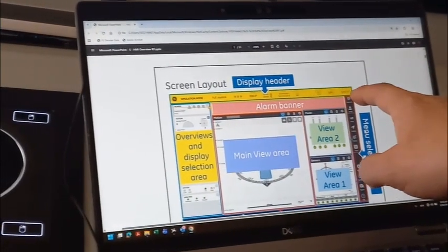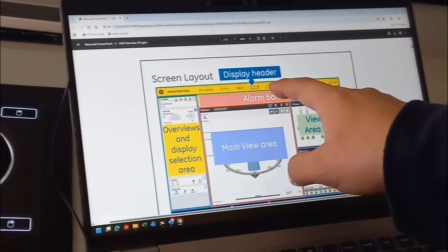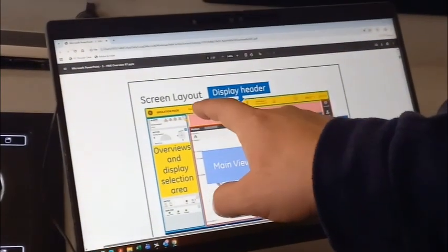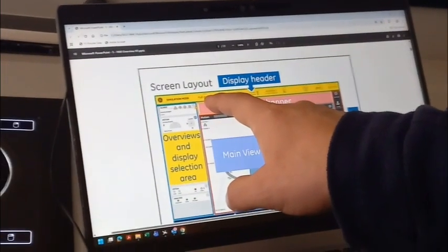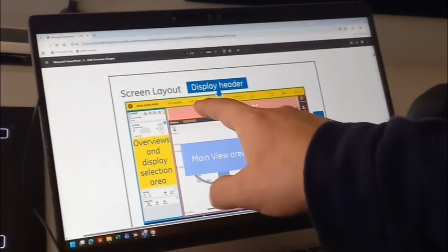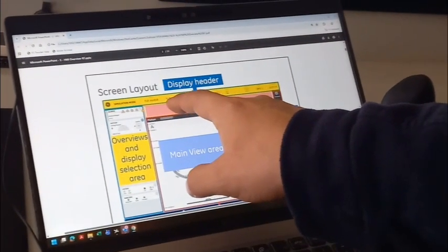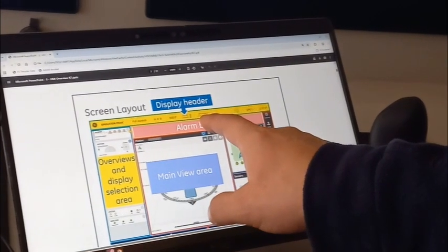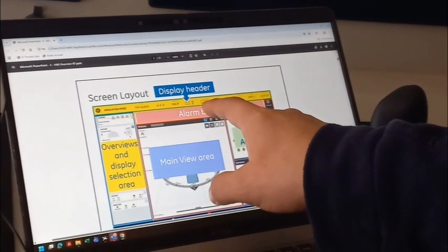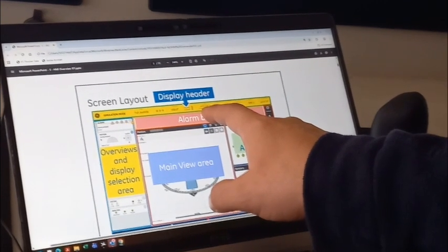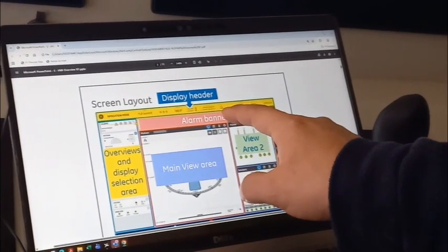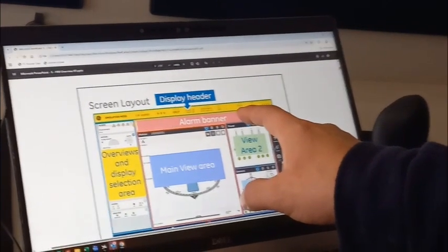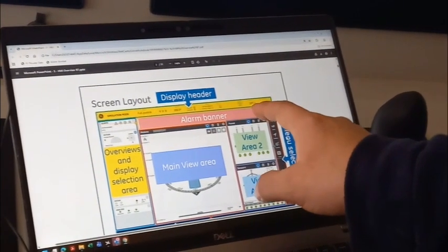The first upper banner is the display header to show the mode, if it's in simulation, and the mode of the control system, and the 3x which is in control, the heading of the vessel, the speed of the vessel, and the GPS fix north, west, or northeast, and the control gains, traffic indication, and the workstation which is in control.